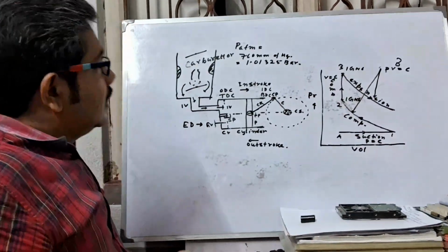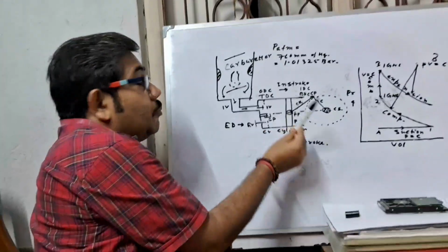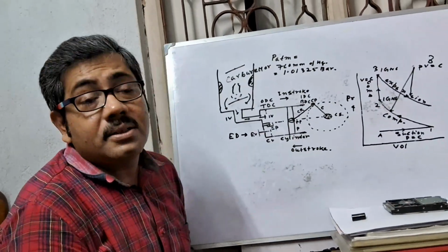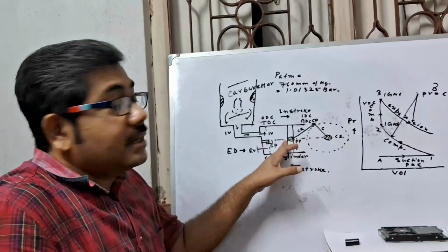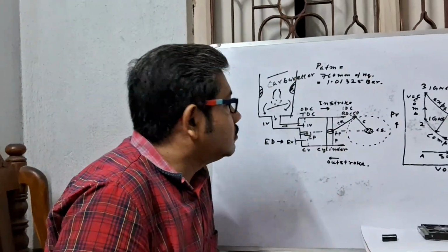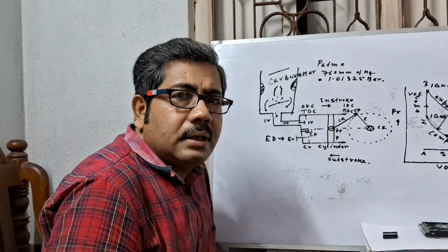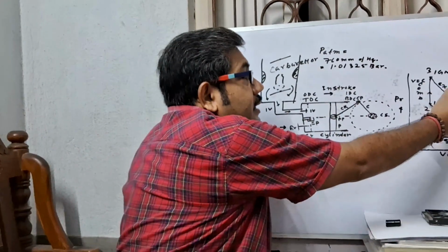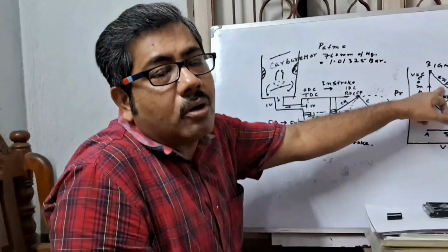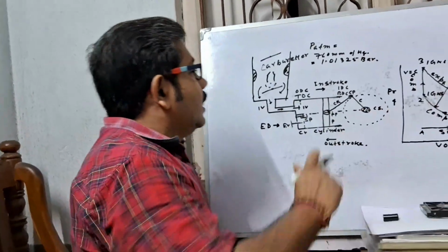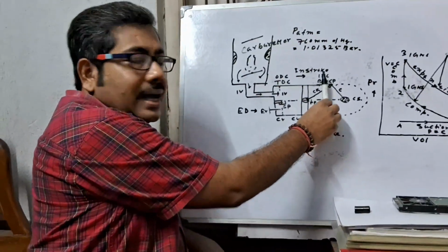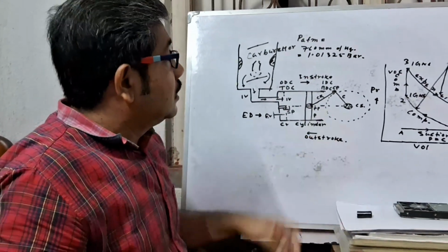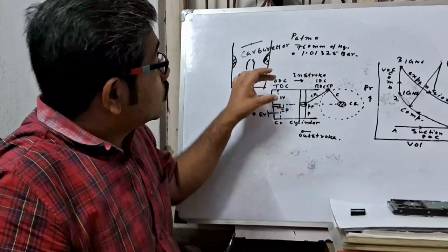This is also an adiabatic process, and this is expansion. When the piston moves from TDC to BDC, expansion is completed, and when expansion occurs, work is done by the burnt gases on the piston. Here it is also called the working stroke or power stroke. Now the piston reaches BDC, and the heat energy of petrol is converted into mechanical work. This is called the power stroke.